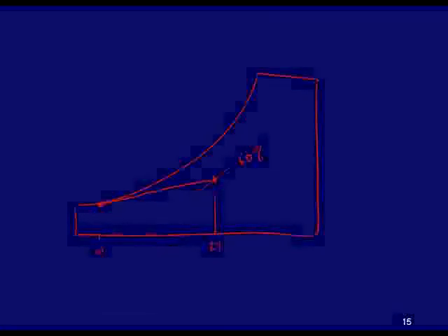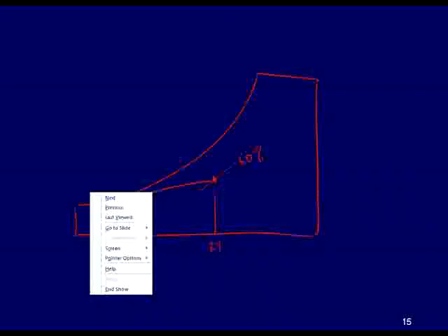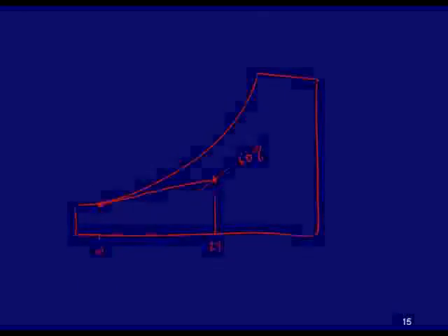Now I gave you the data we solved from the energy balance and the mass balance, but you can also do that on what we call a tie line. Our resulting mixture will be halfway in between, and then you can read off the temperature and the other properties, and so on and so forth. I believe the enthalpy we said was 45, and the omega was 0.0104.